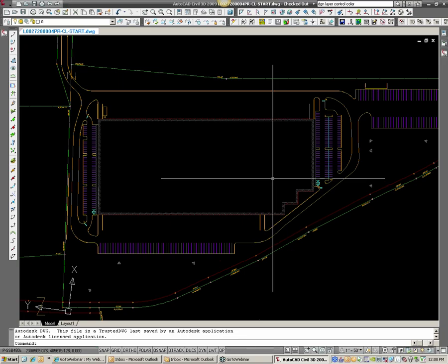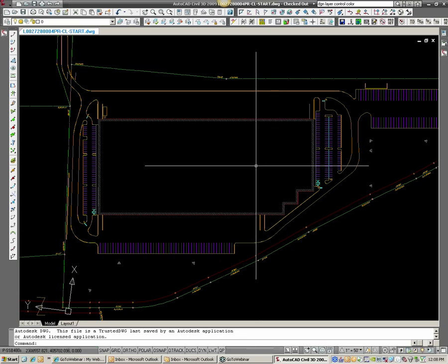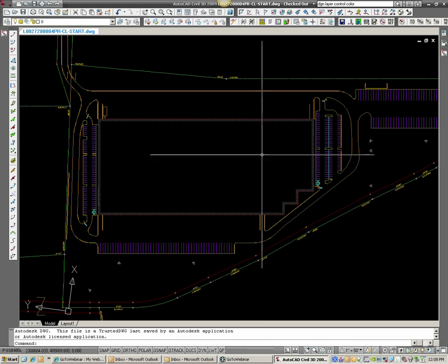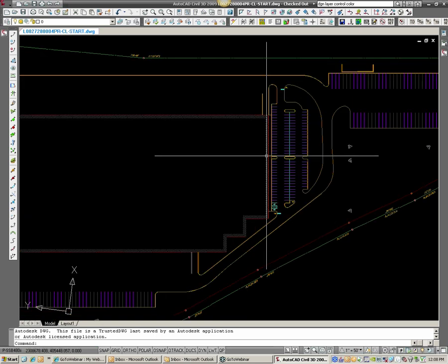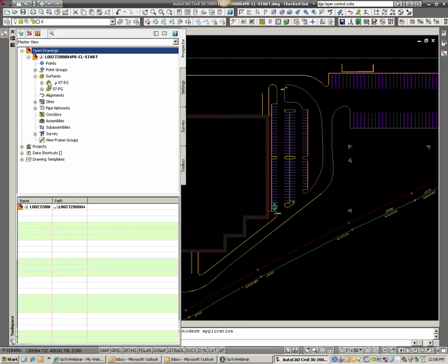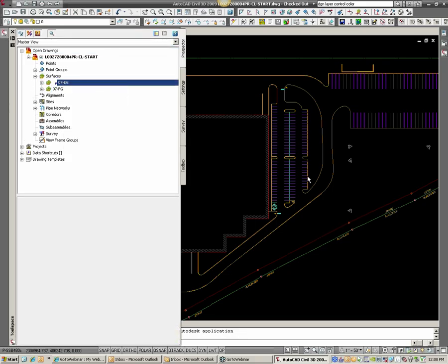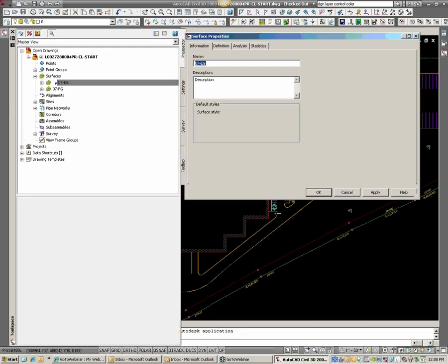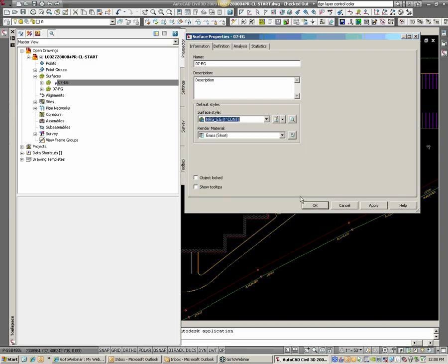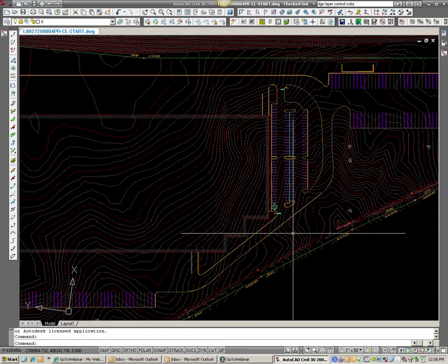So on a commercial site, you're always coming off the building pad. Always, always, always. I can't say it more than that. You're always coming off the building pad, the first floor elevation. Now, how do you know what that first floor elevation is going to be? Well, you can do some quick math, look at your grades over here or over there, wherever it's going to seem tight for you on the site, and try to guesstimate a first floor elevation.